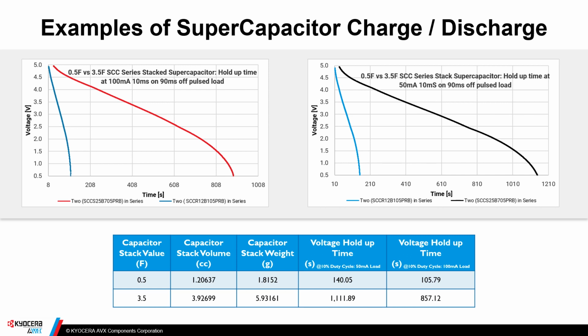There's many more different types of these curves, different voltage ratings, etc., including ones for those large 3000 farad parts and the exceptionally large modules, maybe 48 volts at 165 farads or even larger. So this type of data exists. This type of information is easy to access. There's some calculators for it, and we'd very much like to help work with end designers to size these components for any size load. It could be IoT or larger.